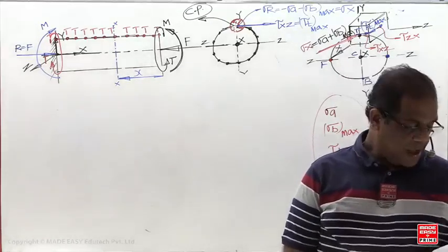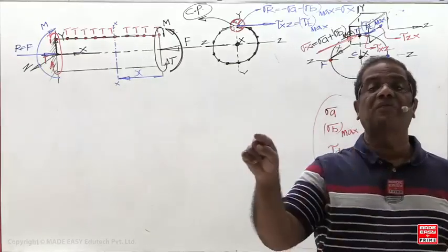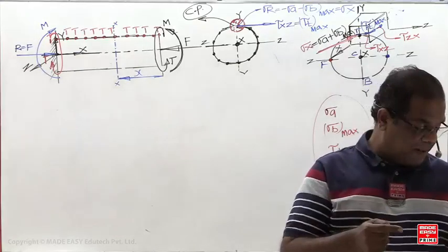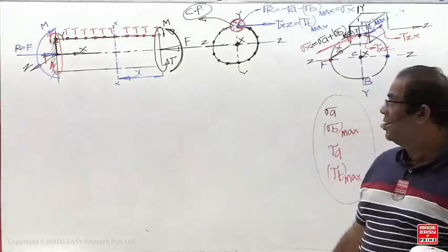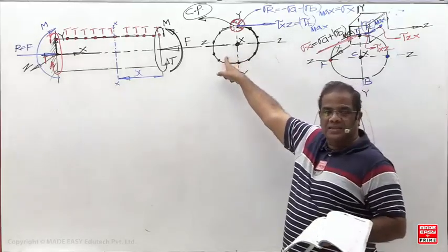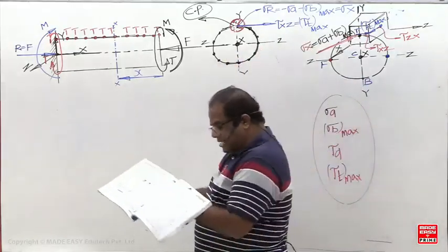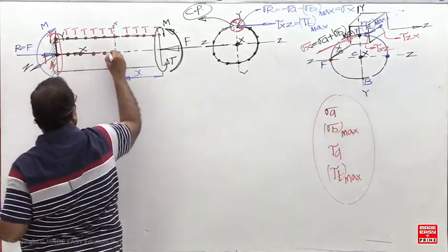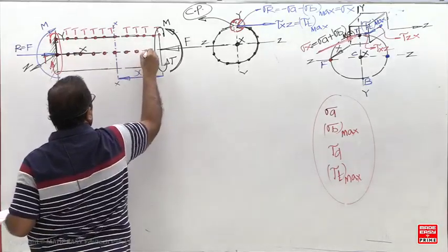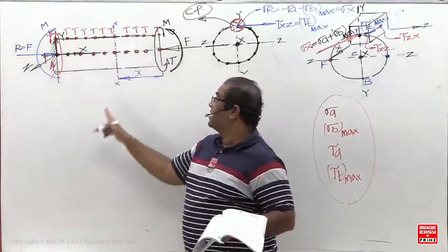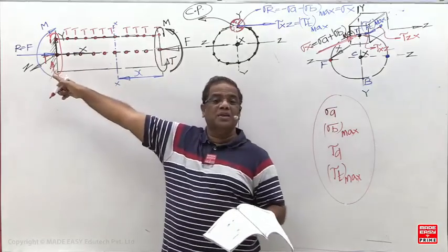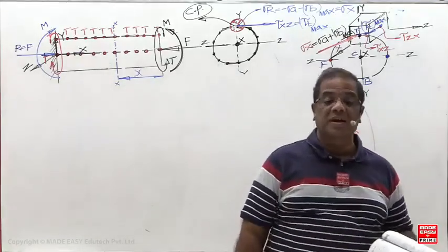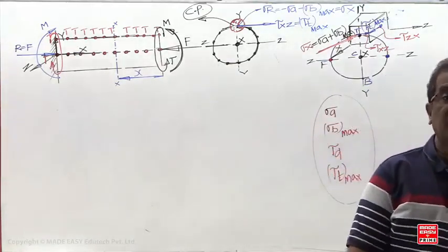And what about the last one now? Axial longitudinal fiber. What is the meaning of axial longitudinal? Longitudinal axis. The axial longitudinal fiber of the shaft is subjected to compressive stress. At the centroid, which stress is there? Only axial stress. Bending and torsion are 0. At each and every point on it, bending stress is 0 and torsional stress is 0. Only axial stress is there. So for the given question, which statement is correct? Option D is correct.